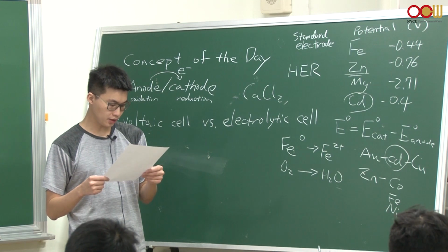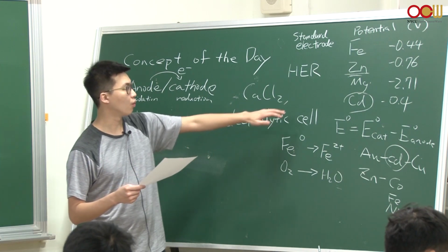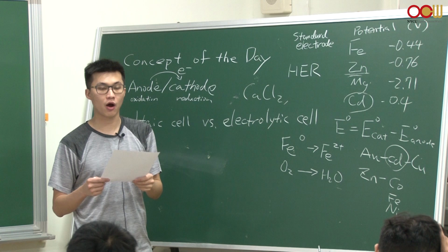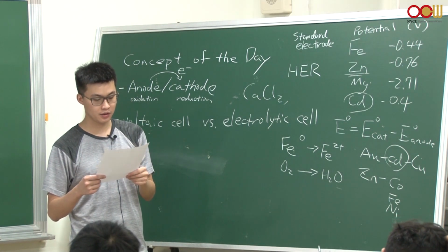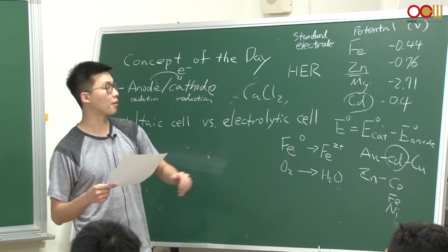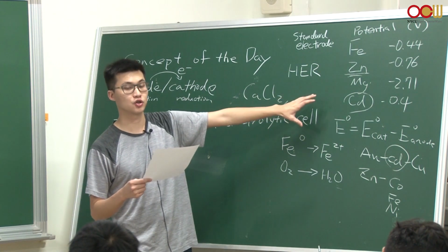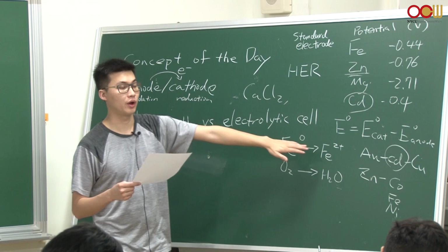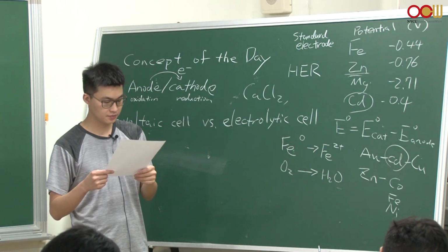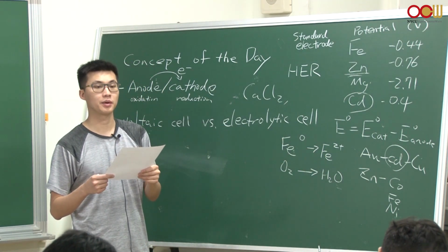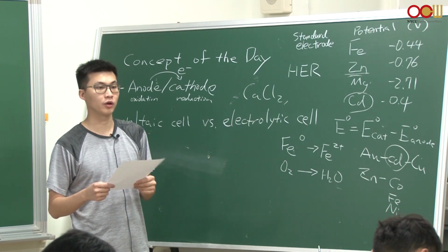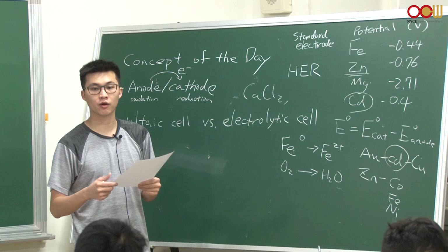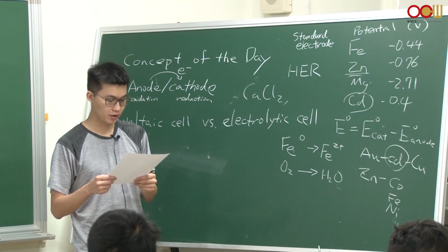So why do we need to do electroplating? The first reason is we want to protect our metal, and second is we want to have some surface property or even change the mechanical property when you can deposit a certain amount of alloy material onto your surface. And also sometimes it's just for the appearance. Nobody wants to buy a dull looking structure, right? We like our structure to be shiny and pretty.